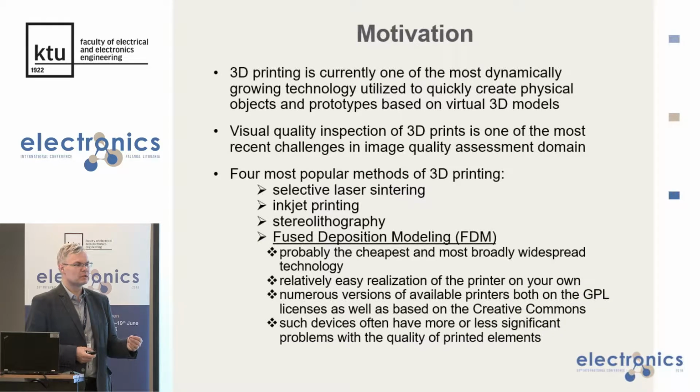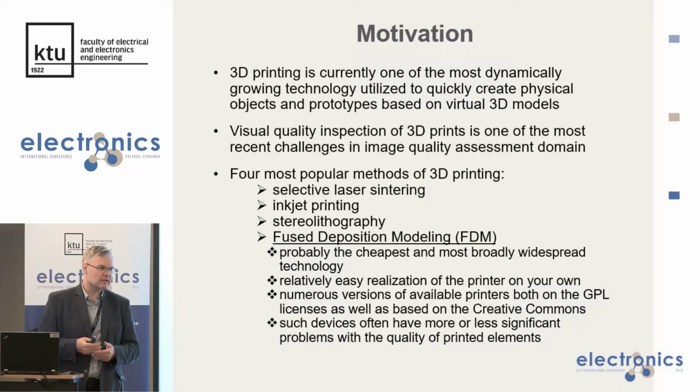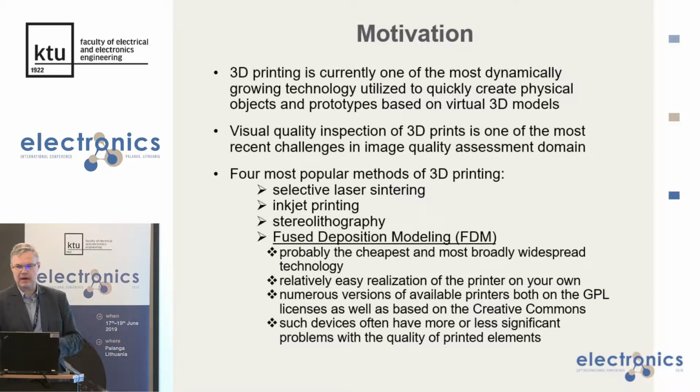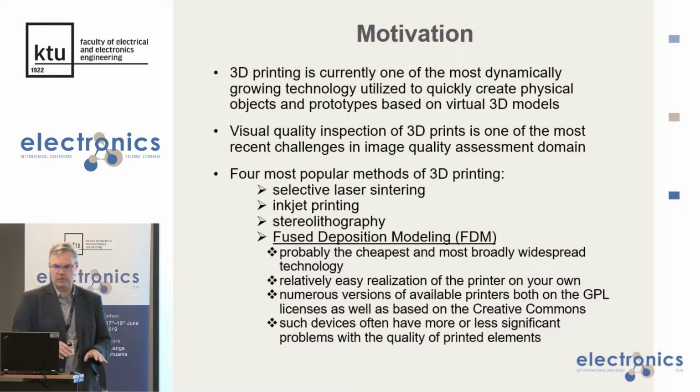Of course, you can try to check the internal structure of the 3D printed parts, but we focus on the vision. Why? Because our aim is to correct the 3D printed surface even during printing if possible. So if we mount a camera, we can not only monitor the progress of printing, but also try to correct some small issues or just abort the printing process in case of detected very low quality, just to save the material, to save the energy and time as well.